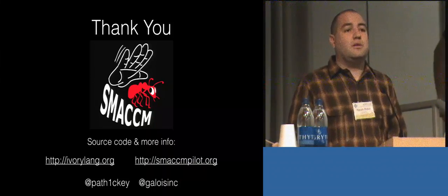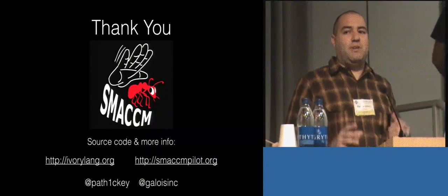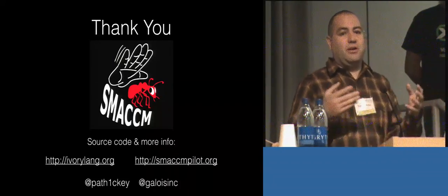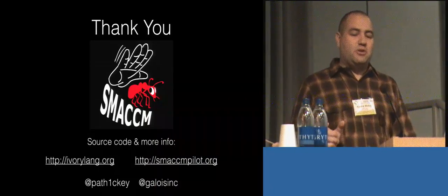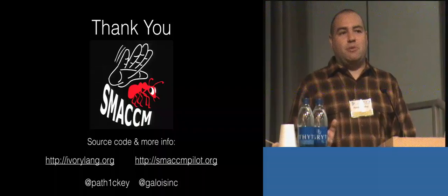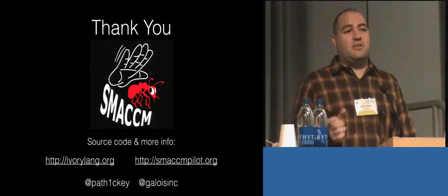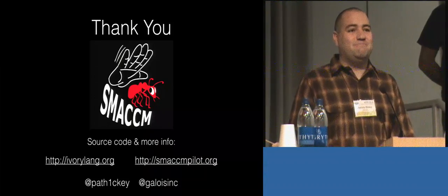Okay. And my main question is, yes, we all know the advantages of DSLs, that it's of course an embedded DSL, and it's very easy to get off the ground. But there are some problems, for example, with error messages, right? Oh, absolutely. The big problem with error messages in this is that you have to be both an embedded systems programmer and a Haskell programmer. For certain things, if you put the wrong number of arguments, you might get a kind error. You have to know the way in which we implemented the Ivory language. You have to go into the source there and look at the type family to understand those error messages, which can be quite difficult, and that's a significant thing we'd love to improve upon.